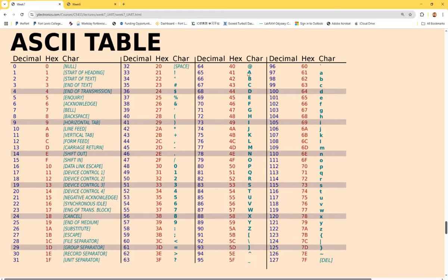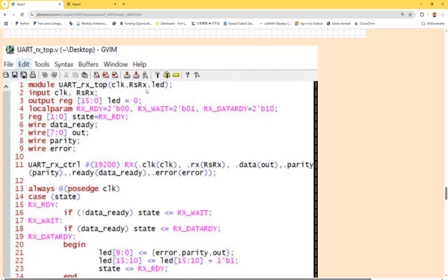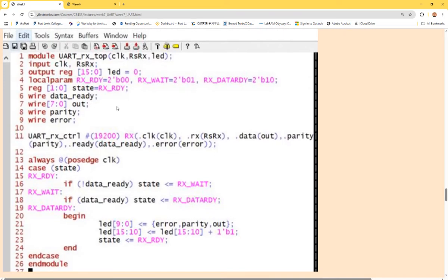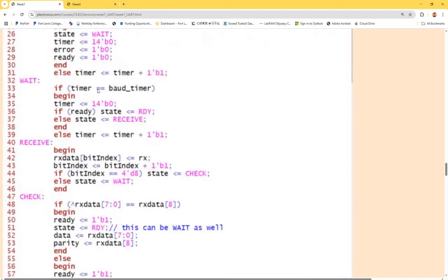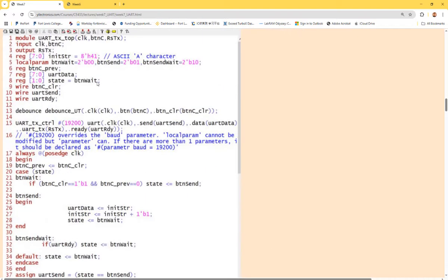So initially, if you pull it up, your top module here is just giving an internal byte. Oh, not this one. That's RX. And for TX, here. See, it's a constant. It's being put in the register. It's giving a 41, so 41 hex number to the UART module as an 8-bit parallel input, right?